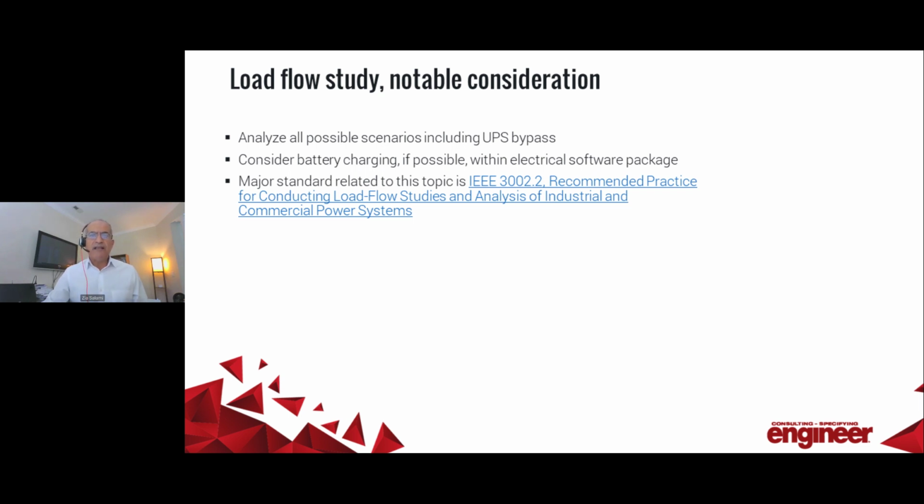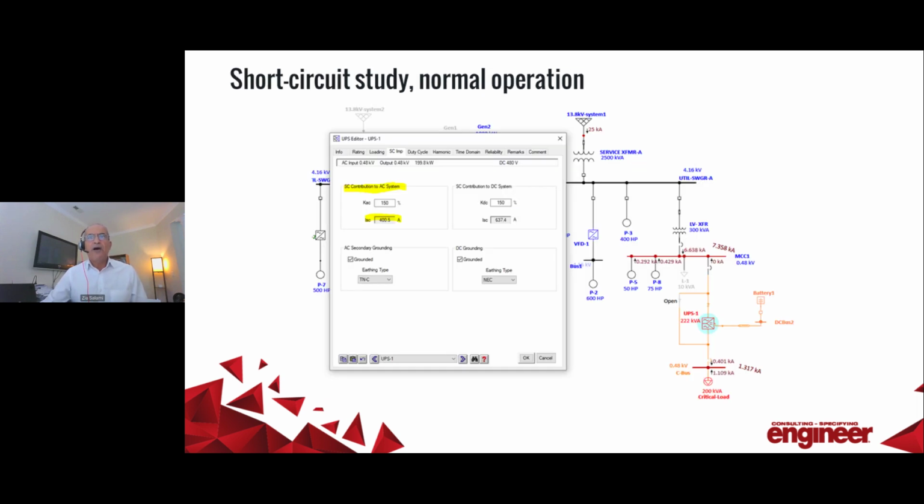The main standard related to load flow, which I just want to point out for information, is IEEE 3002.2. Now let's look at the other study that is important for sizing the circuit breaker, sizing the bus switchgear, and the withstand capability of the equipment, which is the short circuit.